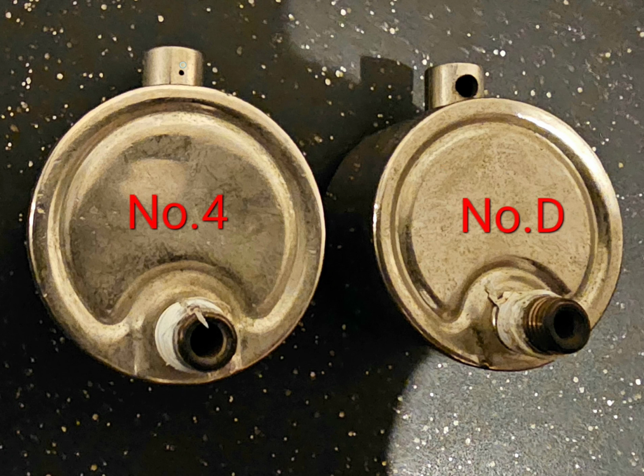This over here would be better for a radiator because it has a smaller outlet. And the way these things work, they work off of temperature. And if there's air mixing into the same compartment of the radiator where this vent is located, guess what? This vent is not going to close. Or it'll close, but it'll continuously keep venting, opening and closing, or just gradually venting to let the air out. This is the personalities, or the characteristics, I should say, of these vents.